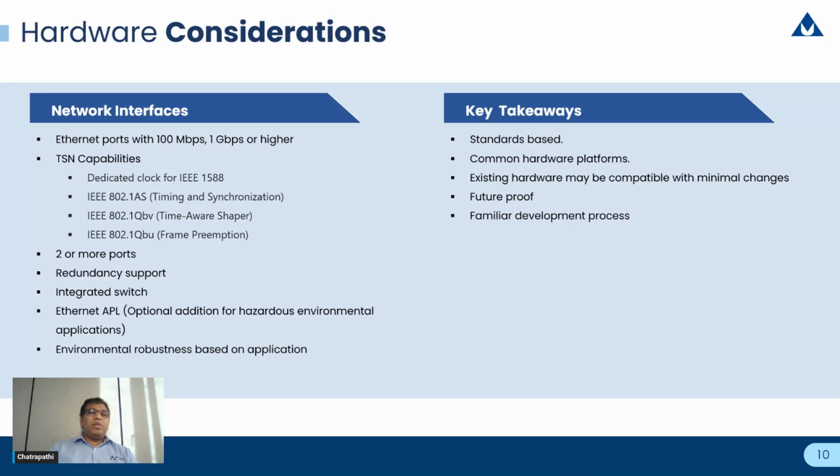Components are available from leading vendors with TSN capabilities and integrated IEEE 1588 clocks, and then supporting all the TSN related capabilities with drivers supporting different operating systems and development platforms. So having such an integrated switch makes it easy to adopt all these network interface requirements.